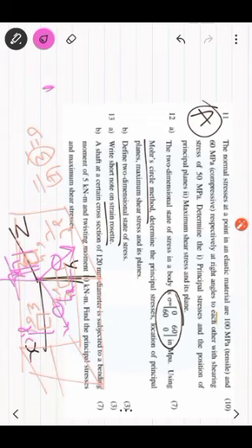We have already put nx, ny, nz, that is the angle alpha, beta, gamma. Multiply the x direction with this one, you can get the direction along x, y, z. So this way you can use the strain rosette to find the stress along the x, y, z direction, and then you can convert it to any direction and find out maximum stress.